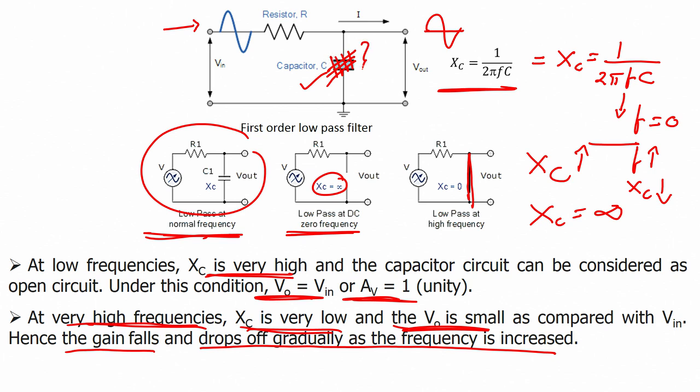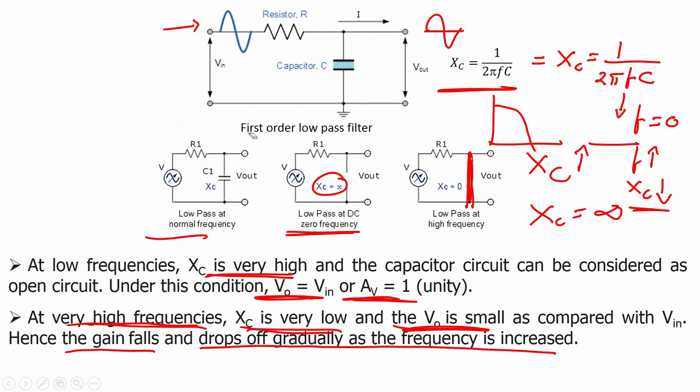In this case, at lower frequency it was not conducting, now it is completely shorted, because at high frequency the Xc would be less, and that is why it is shorted. That means the output you will see slowly fading down, and finally there will be no frequency that can pass through this particular circuit. Alright, extremely easy. You just have to understand the role of the capacitor.